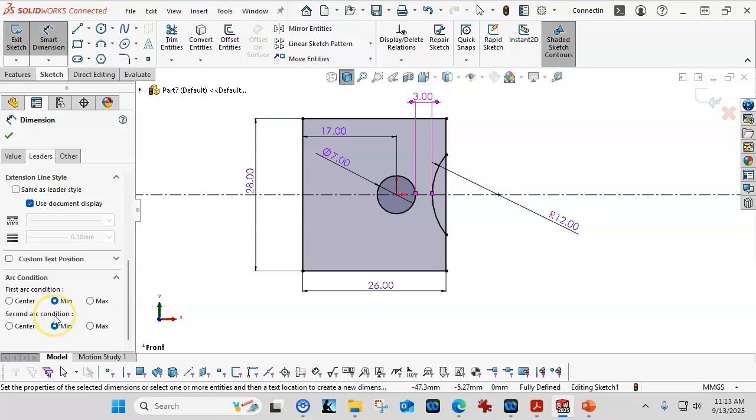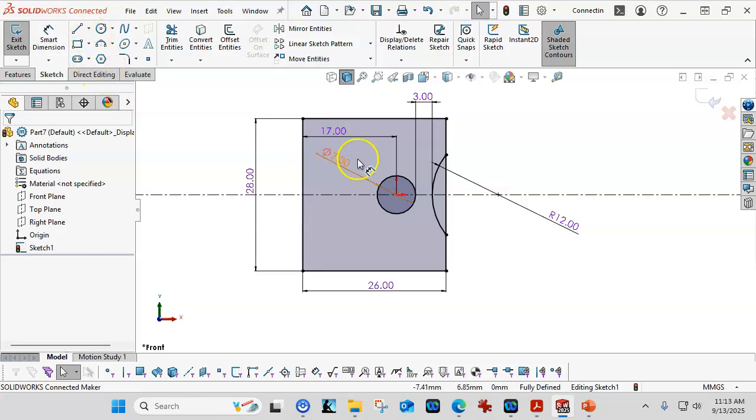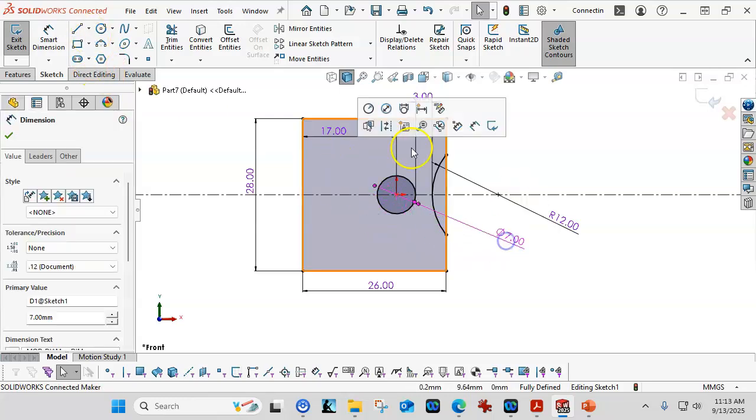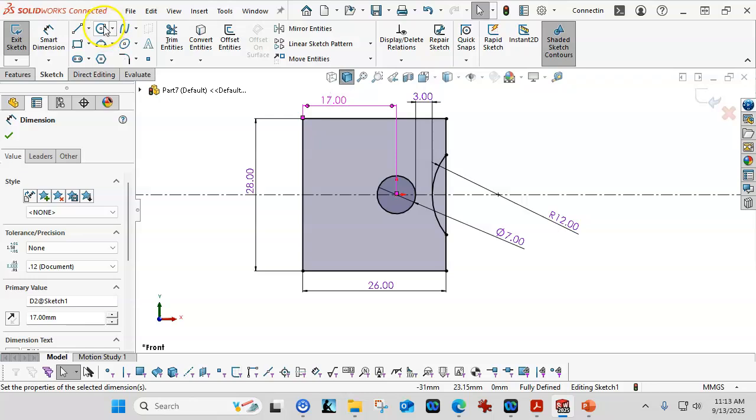I think it was 2.3, I used the example that if somebody broke that flange and we can't order another one because the machine's 50 years old and they don't make it anymore, and we have to reverse engineer it so we can manufacture one, I'm probably going to sit there with calipers, measure to the outside, get a number that's close, and use my max conditions or my min conditions to verify that geometry. So whatever makes it easier.